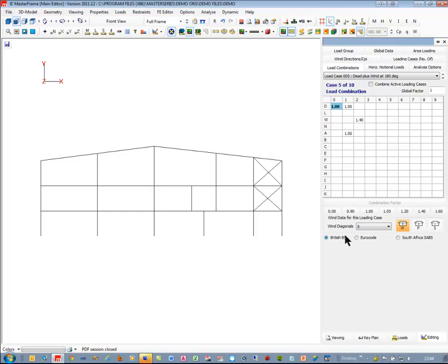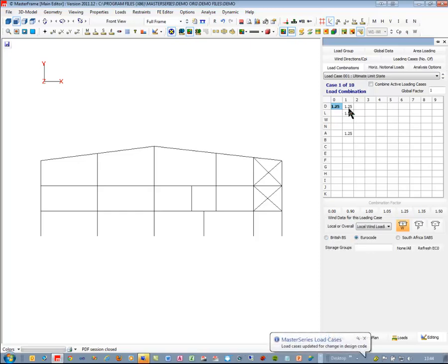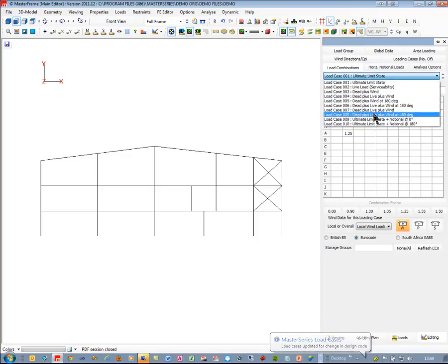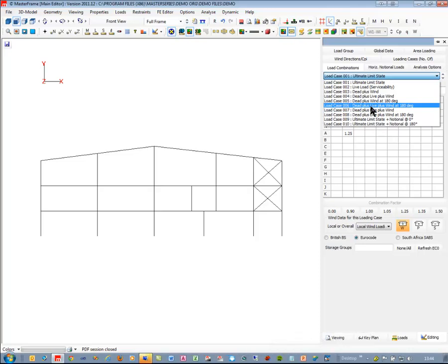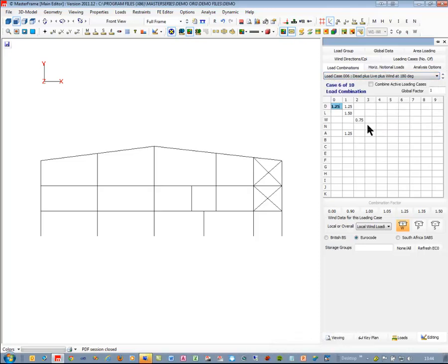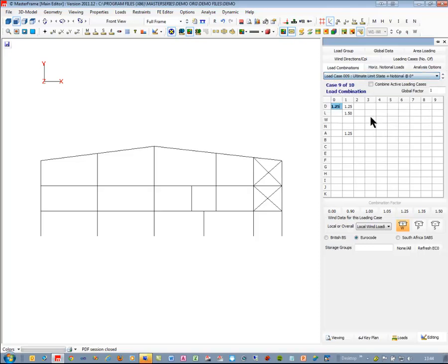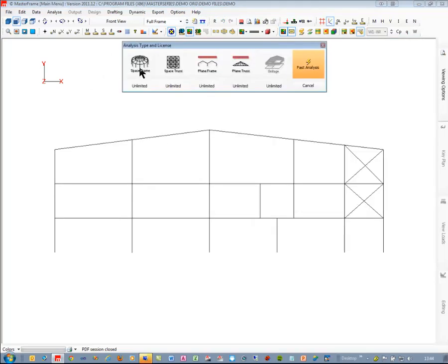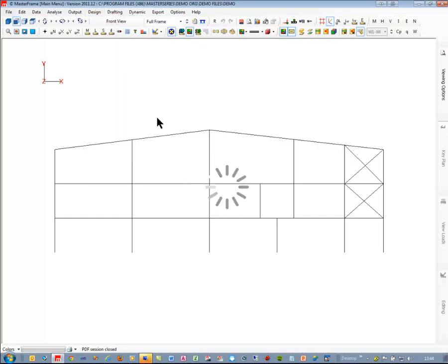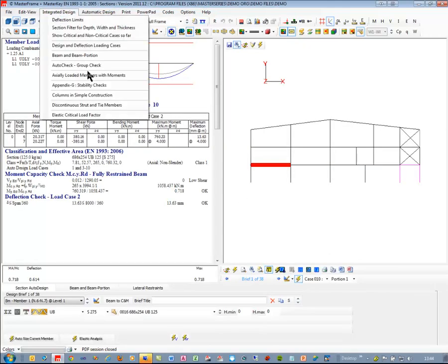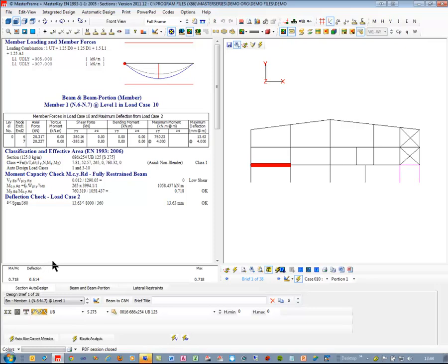So what I would ask it instead to do is the Eurocode equivalents. So we're going to get our 1.2s and 1.5s. We're going to get differences in it. We're going to get dead plus live plus wind at one point. We're going to get those reduced, so we have the dominant and the not so dominant loads, and we don't get separate notional loads on their own inside the Eurocode. That's all handled separately. So we just go through and analyze, space frame, design, steel design, and you would apply your checks the same way as I've just done, and you'd look at them the same way.